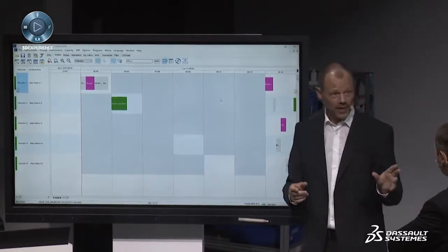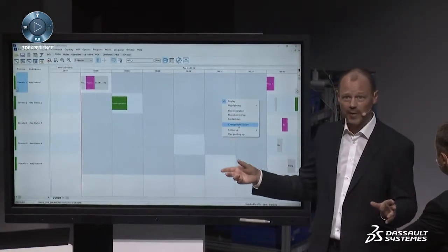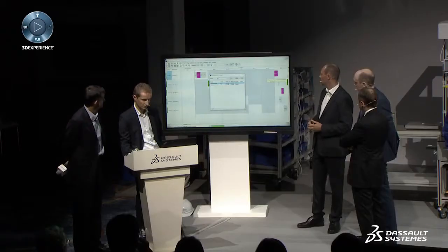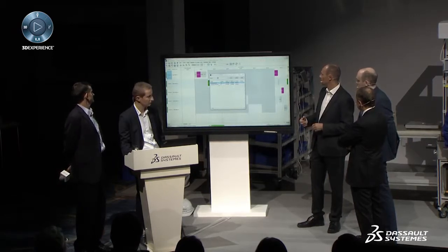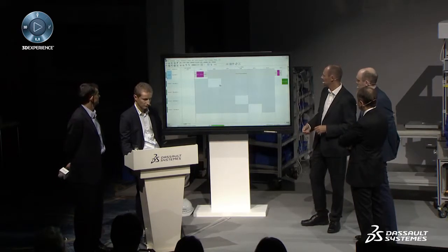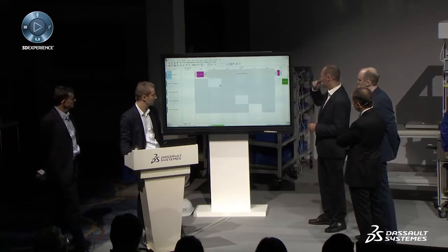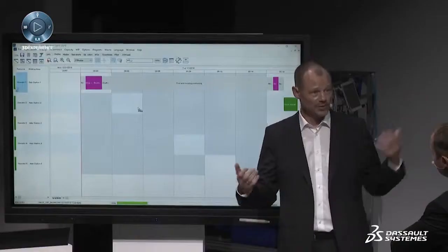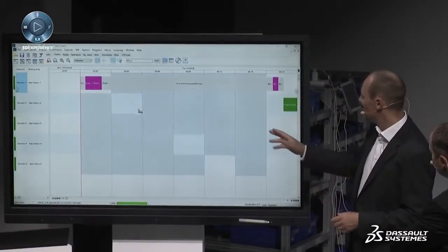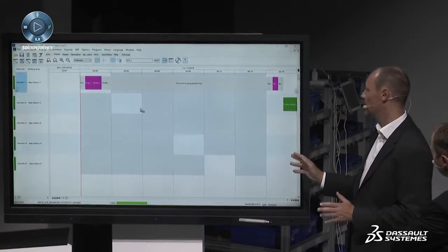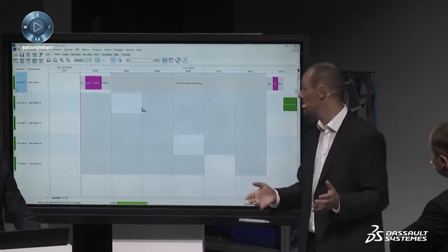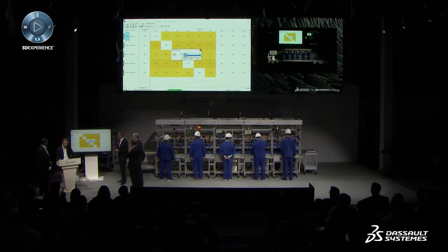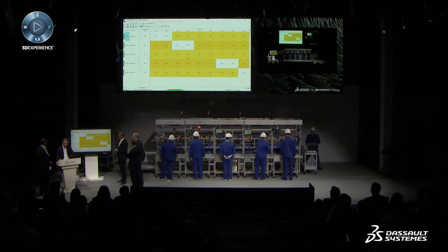What we can try is, because we have a second routing, which we saw before in our work plan, let's try if the second routing is working here. We change our simulation, our test, to the second routing, and we simulate this. It looks a bit better because we have many more operations connected now to stations 1 and 2, which are already available. But we see it is not working in our takt time. Maybe it helps when we just double the takt time from 3 to 6 minutes. Let's check what this idea brings us.